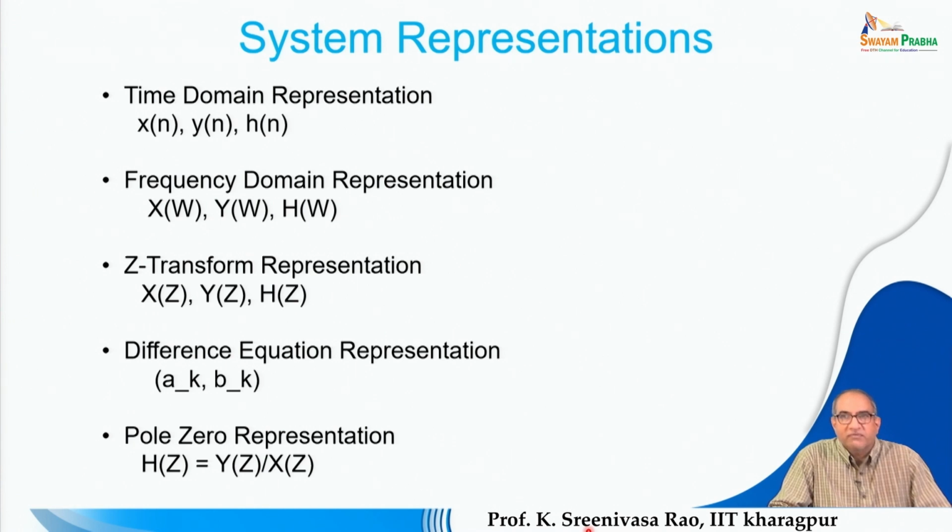So, in that context, for visualizing a signal or system in the frequency domain, we need to use the Fourier transform, with which time domain signals are transformed to the frequency domain, and you are able to see the frequency representations of a given signal or a given system response. So, what are the various frequency components present, and how is the energy distributed among the frequency components observed in a signal in the frequency domain.